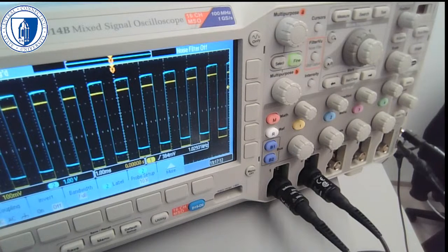Now what oscilloscopes do is they let you see the voltages, right? We're going to be using sinusoidal voltages, and in the first lab, the phase one, we want to see the phase, right? We want to put in a sinusoidal voltage, and we want to see that the voltage phase is different from the current phase when we've got the voltage across a capacitor or an inductor.